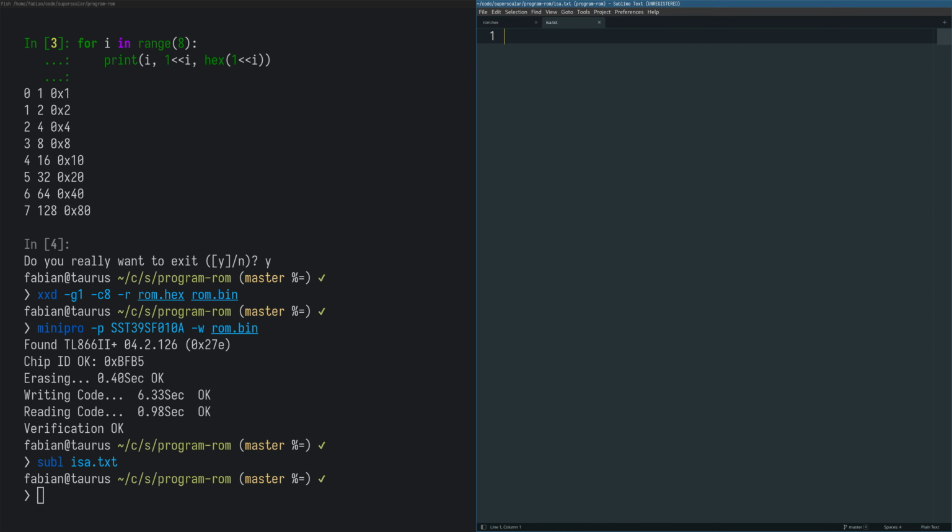So the way we have connected individual bits of the instructions to the program counter is as follows. We have 4 bits which are used as various jump offsets, followed by 2 don't care bits, which we can set to zeros or do anything with them, and then 2 mode selection bits. So basically what this means is if we have 2 zeros at the bottom, which is basically the select lines being all zeros, this corresponds to regular stepping mode.